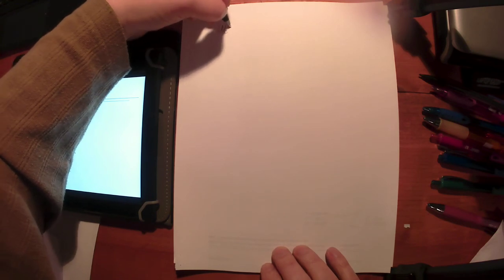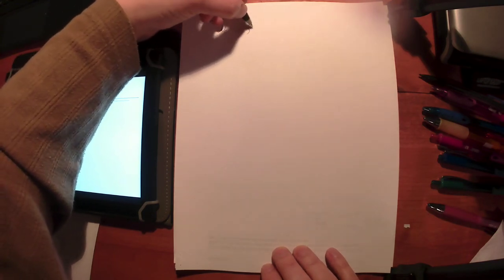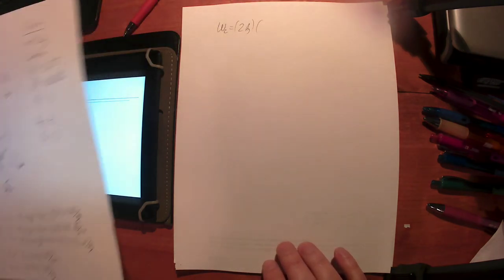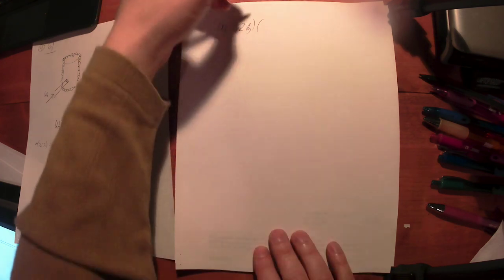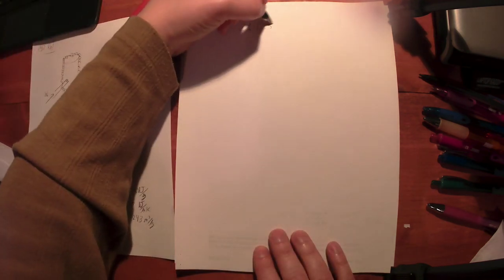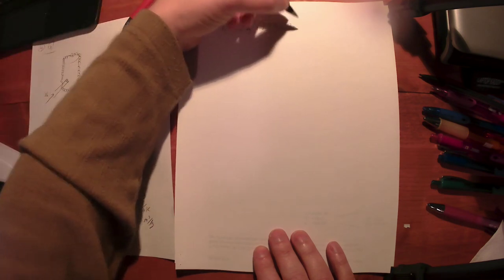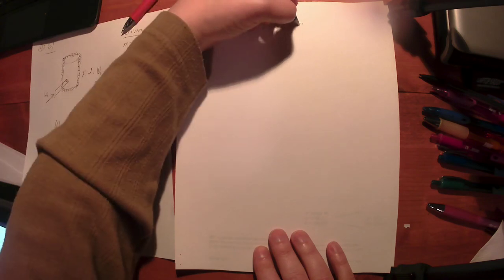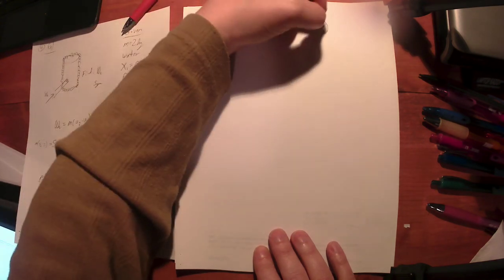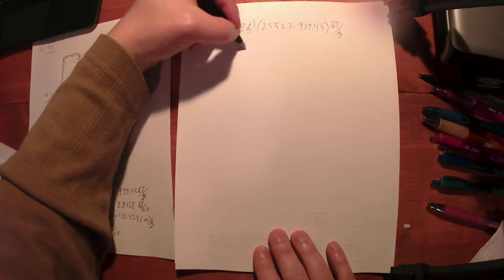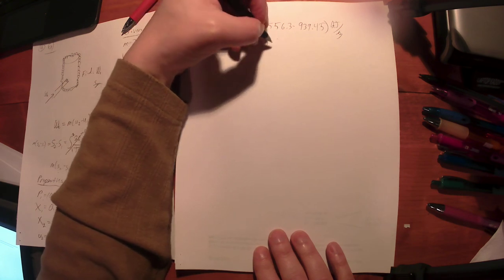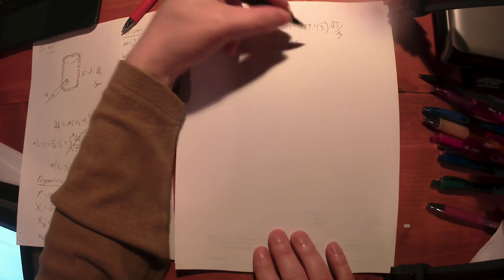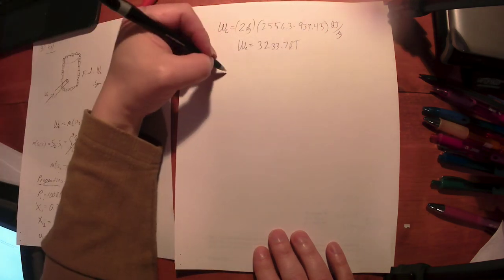Okay. The work, being the mass, 2 kilograms times our U values. All right, so I've got those here. So I do have answers pulled up on my computer over here. That's 2 kilograms times U2, 2556.3 minus U1, 939.45. Both of those are kilojoules per kilogram. So I'm getting the electrical work required to achieve this, to boil all this water off, so to speak. 33.7 kilojoules is what I'm getting there. Make sure you run that through your calculator and check that.